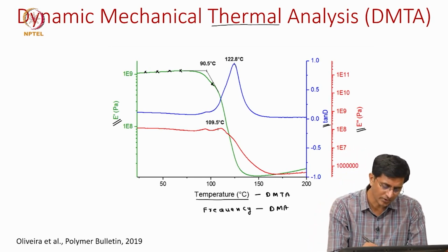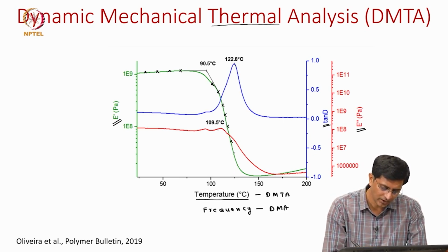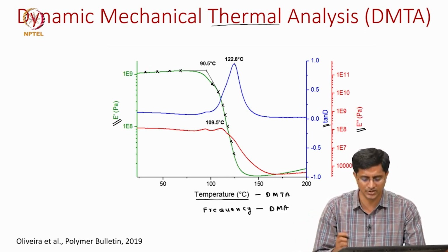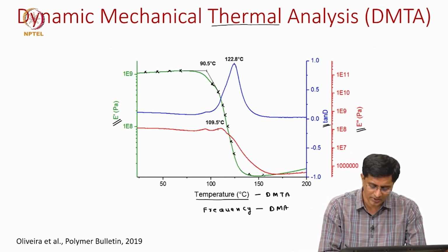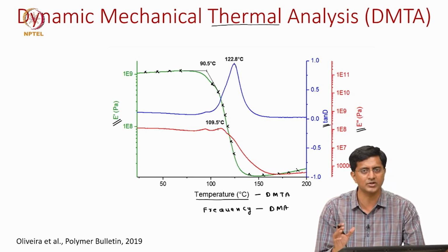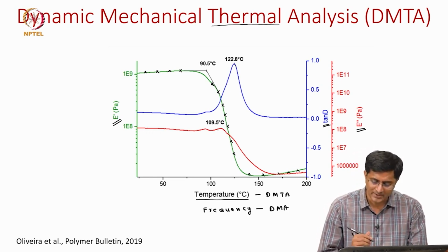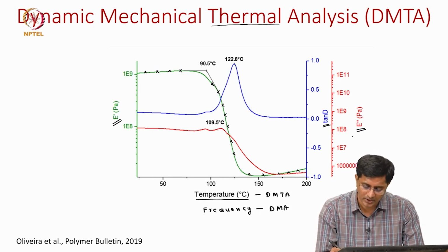So, that is what we are looking at. These storage modulus values are decreasing, but once we heat it up beyond the glass transition temperature, that is when it reaches more or less constant. Here there might be a slight increase, but it is not significant.